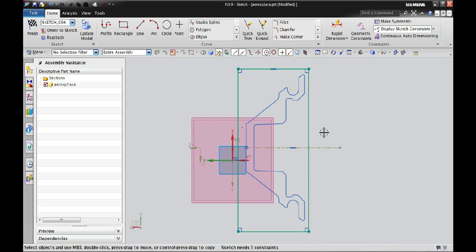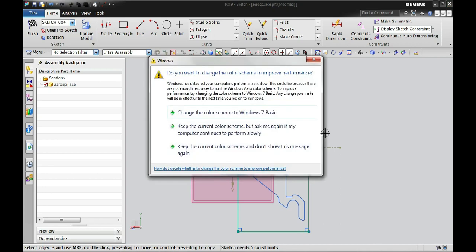Chucking, again for a mill turn you can do a lot of work, right? You can use a long bar feeder, a 12-foot bar feeder. It can be a round bar or a hexagon or different odd shapes. Again, for chuck work, whether it's net shape casting, net shape forging, gross forging, or a simple bar work, you can create the chuck slugs and do that.